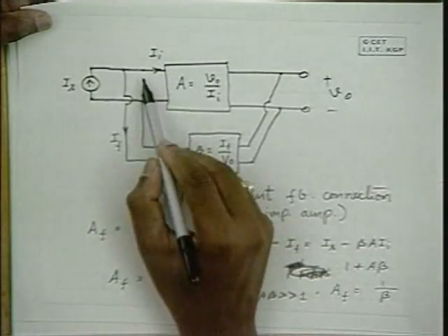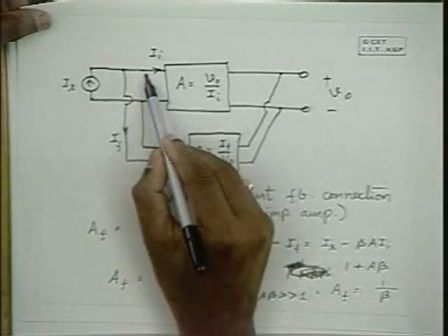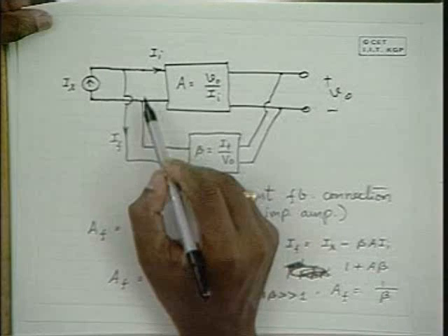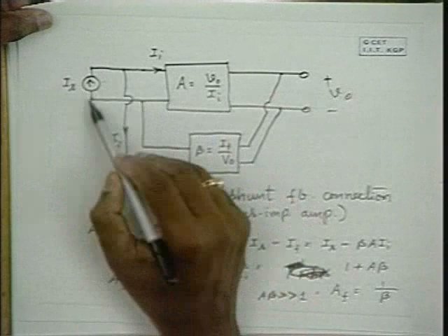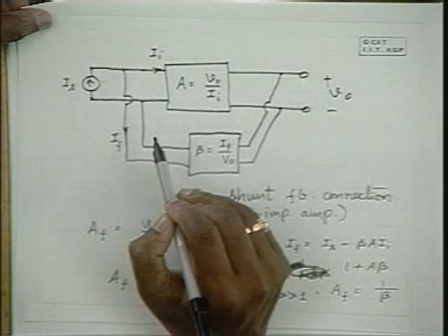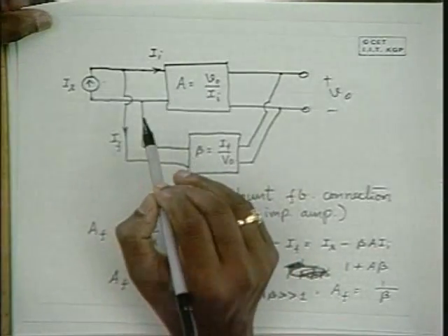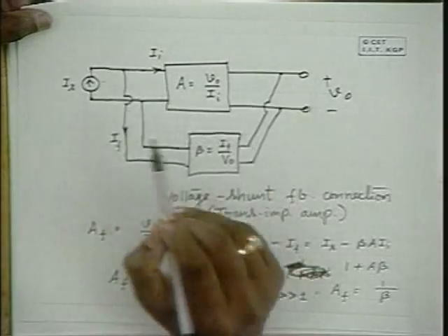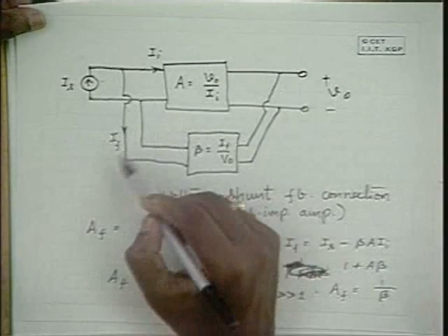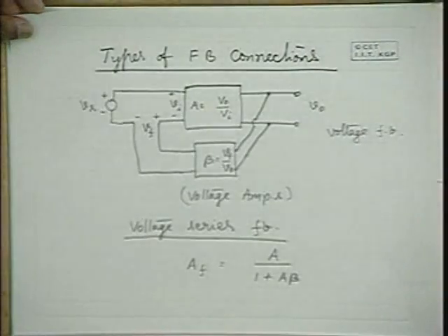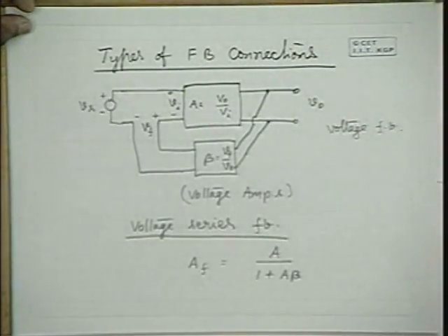So that's what happens when a low resistance is connected. When a low resistance is connected, the current drawn is more from a voltage source I'm talking about. Therefore, the input impedance effectively goes down in the case of a shunt connection. So let us now see analytically how the input impedance is going down.